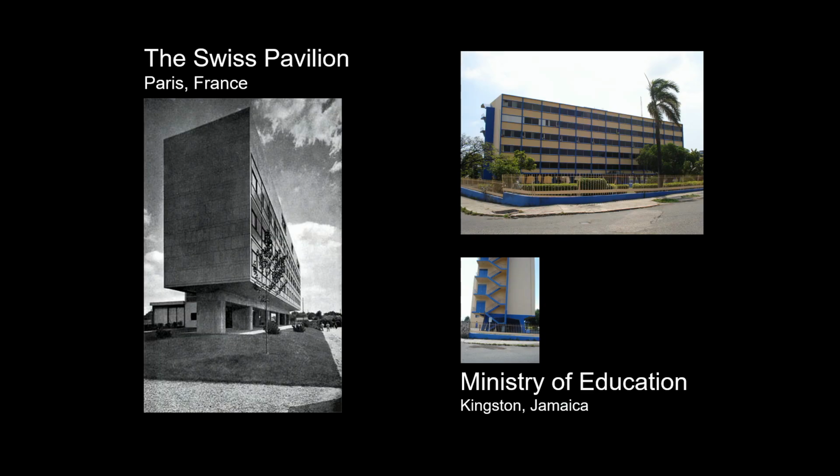The free plan and elimination of interior load-bearing walls, the replacement of masonry and tile partitions by frame and gypsum board, greatly reduced the energy absorption capability of the building and increased its drift, leading to greater non-structural damage and possible structural failure. And 3, the great increase in exterior glazing and the invention of the lightweight curtain wall, like free-standing interior planning, the light exterior cladding greatly reduced the energy absorption capability of the building and increased its drift.